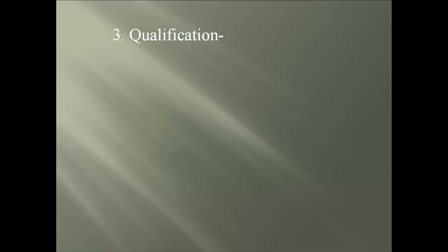As we enter into the last topic of this segment, we'll take a look at the qualification of welding reinforcing steel. The first item is the responsibility that is required for the performed welding, and that would fall onto the contractor. They are responsible for the qualification of both the WPS and welder, plus providing access to these documents, while also providing safe access to the welding equipment and work area for observation and compliance of the material and workmanship. And if any defects are revealed, the contractor holds the duty to repair for approval.